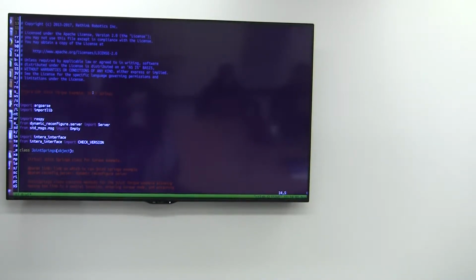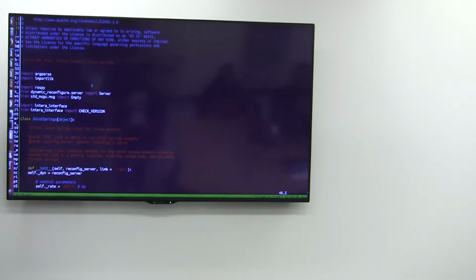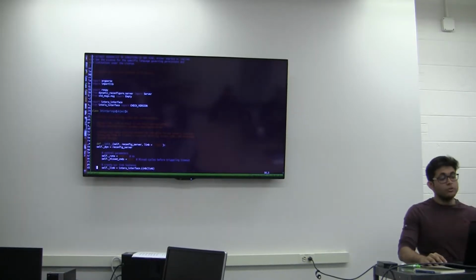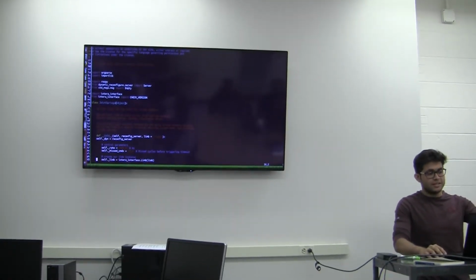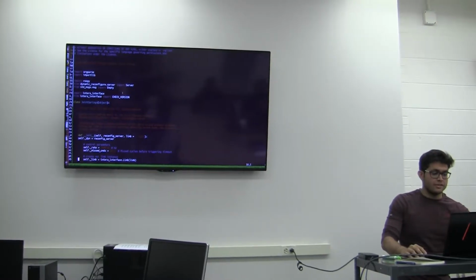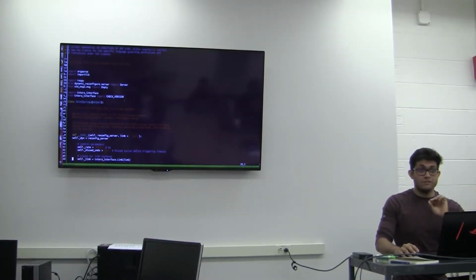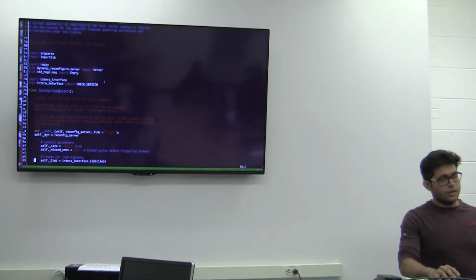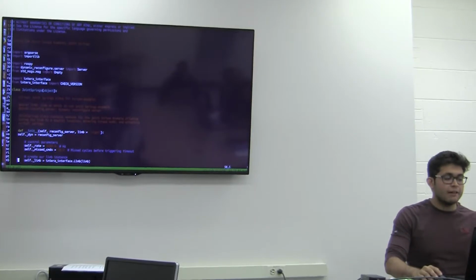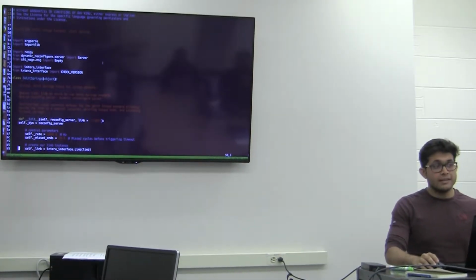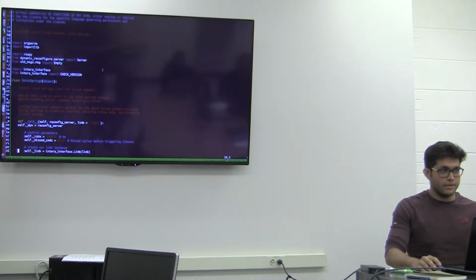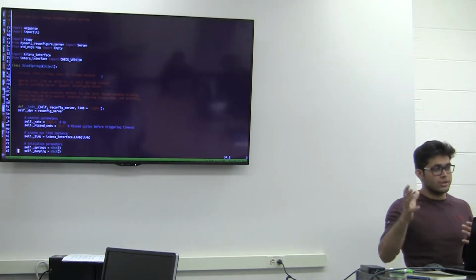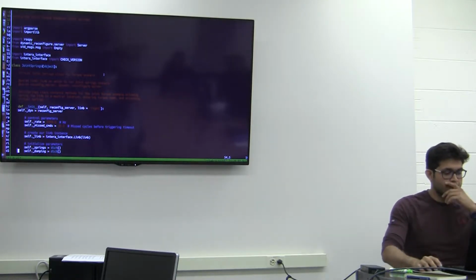Cool. So first of all, import stuff. This is calling the libraries, and what you need to worry about first is the standard messages. These are the messages by ROS itself. Standard messages is the ROS package they are calling here, nothing related to Sawyer. Then they have intera_interface. This is the API for Sawyer, which you call to use all the other functions like close, open, and all that stuff.